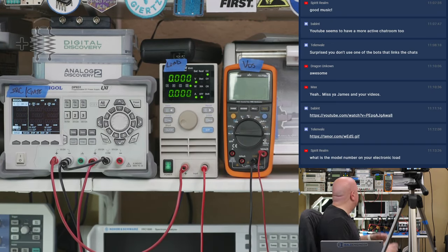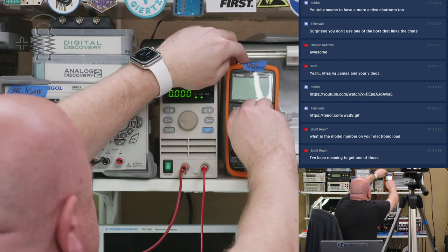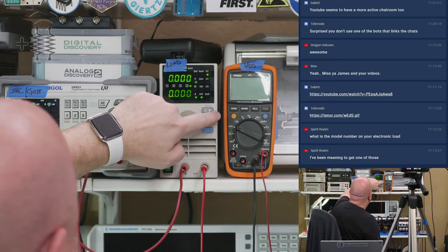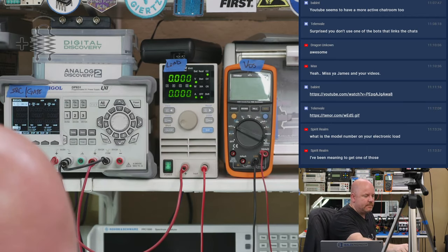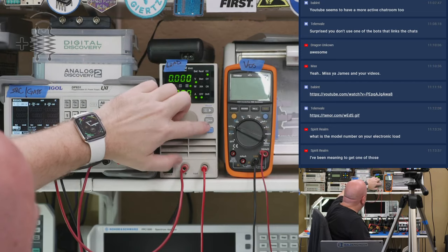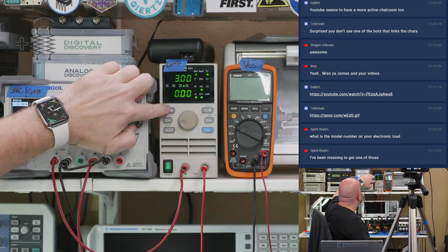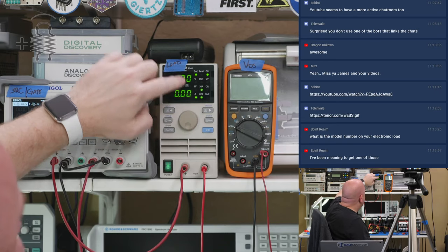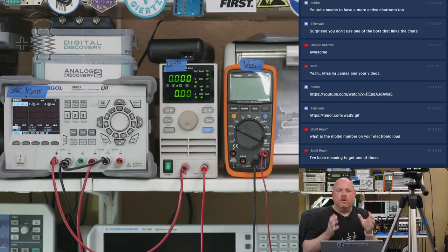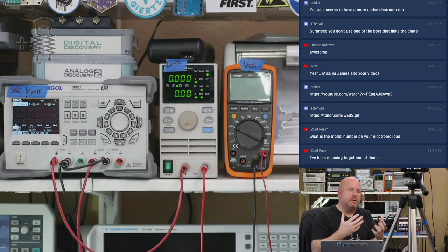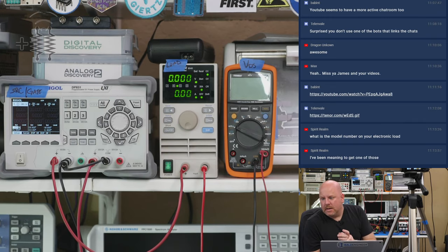Now let's go make a measurement so we can see what's going on. First thing I'm going to do is turn this on. I'm going to make sure that my load is in constant current, with high current range, and now we're going to set this to 1 amp. Constant current means that the load will constantly adjust its resistance so that it is always drawing 1 amp of current. That's one of the cool things about using a load, is that you can set something like that.